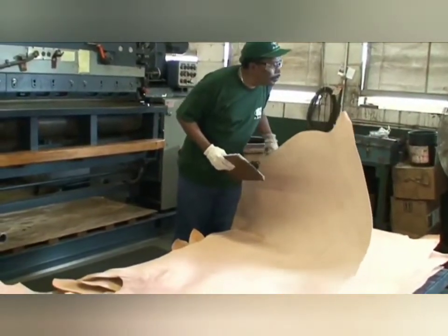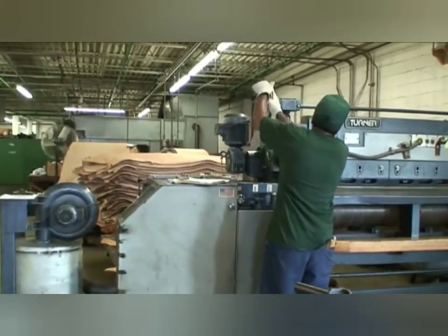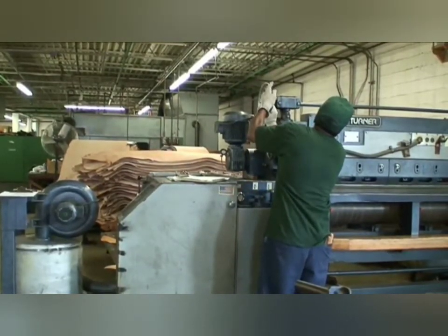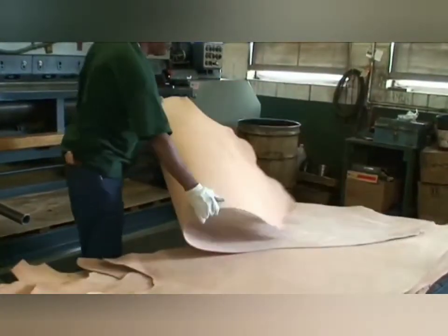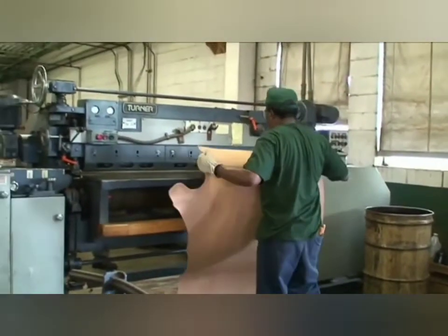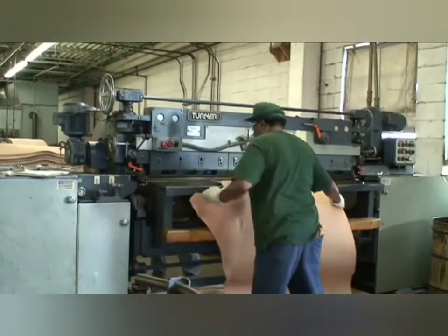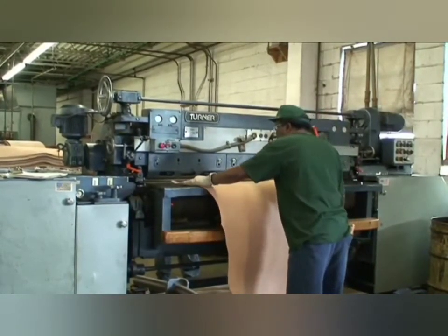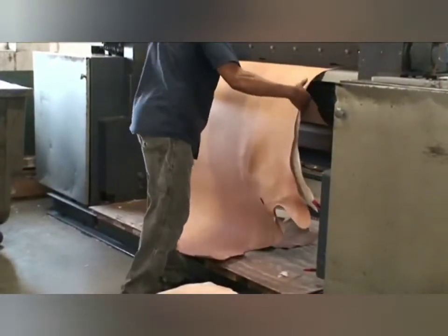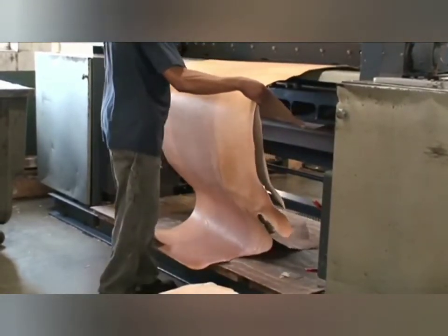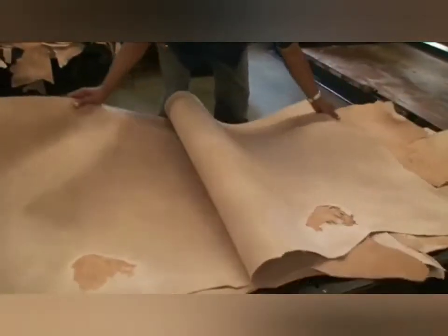Leathers that require exact thickness will be run through a dry splitting machine. This splitting machine is the most highly calibrated machine in a tannery, similar to that of a stitch-and-all sewing machine. Comparing two leathers of similar thickness, the dry split leather will be weaker than the non-split leather because the fiber bundles have been disturbed. The grain layer is for looks, the fiber layer is for strength.